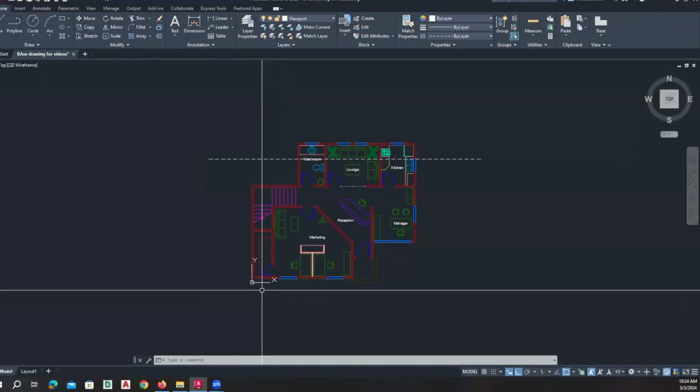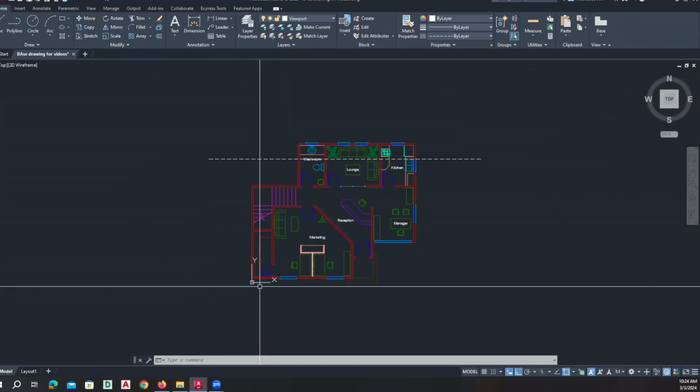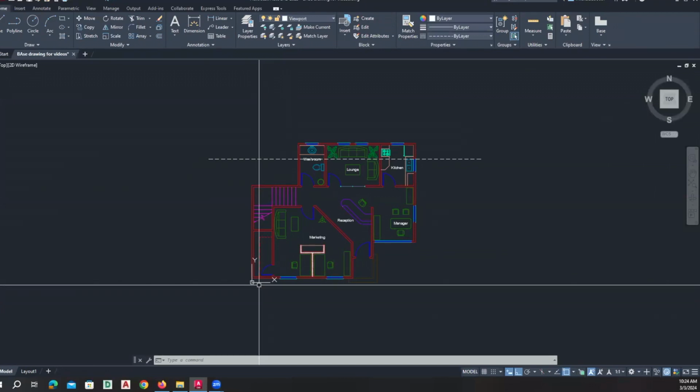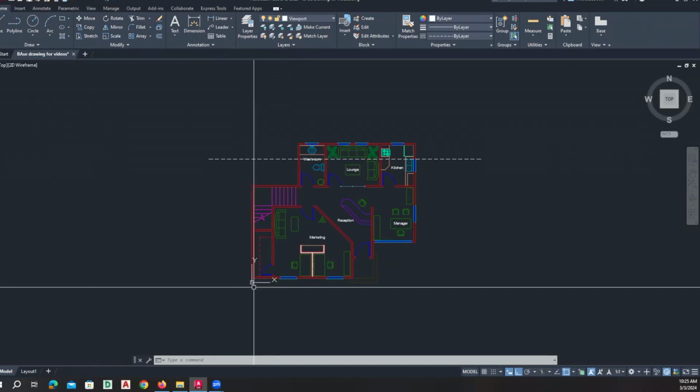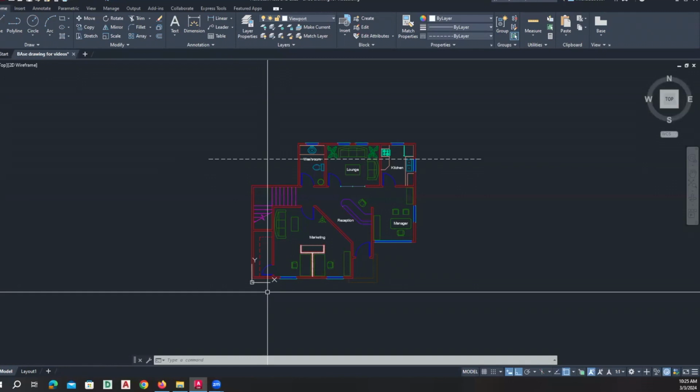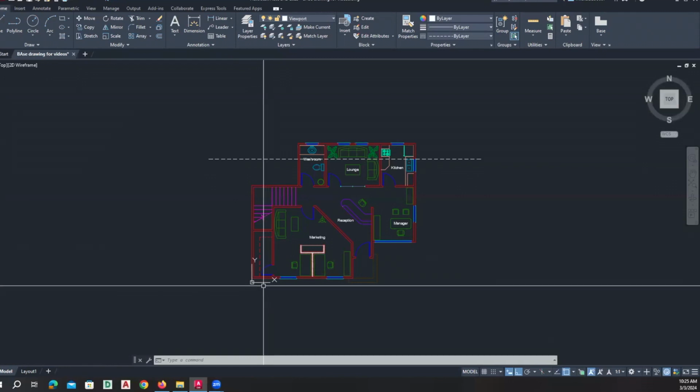Once you move your WCS, for your XY axis, it becomes a user coordinate system, a UCS, because the user is controlling it and it's not controlled by, let's say, the world, right? It's not your standard, unchanging coordinate system.